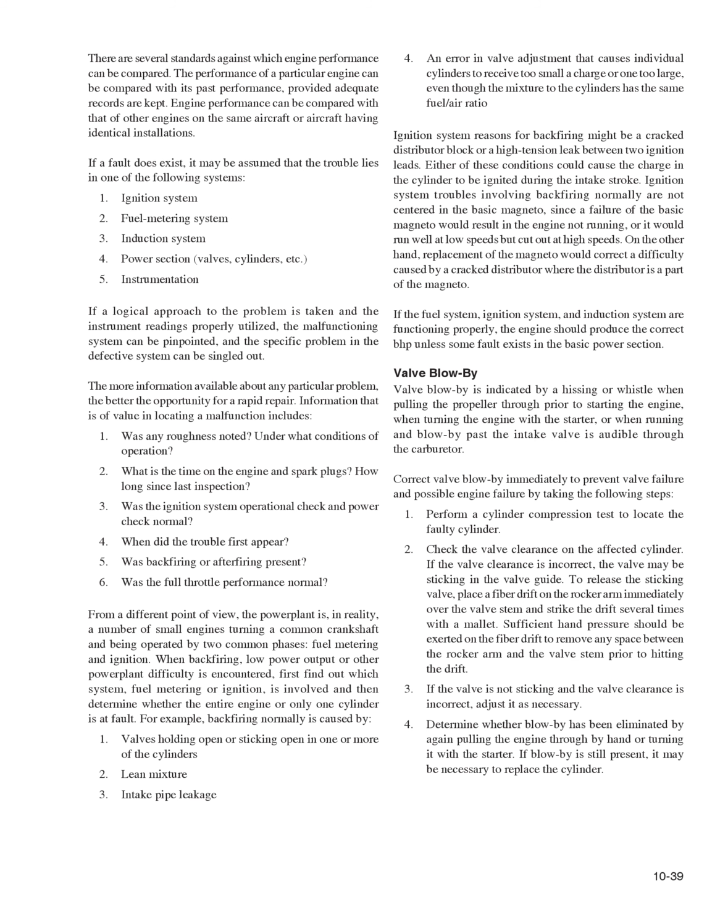The more information available about any particular problem, the better the opportunity for a rapid repair. Information that is of value in locating a malfunction includes: 1. Was any roughness noted? Under what conditions of operation? 2. What is the time on the engine and spark plugs? How long since last inspection?